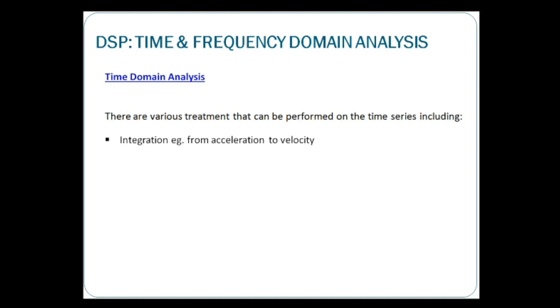So under this time domain analysis, you can do integration from acceleration to velocities. Then we have the velocity signals, and we can get velocity amplitudes, the velocity overall vibration. A lot of times your ISO standard compares with these velocities, RMS, overall RMS. Then you can immediately, in the digital domain, compare with whatever you are referring to in the standards, right? So it can be easily done in digital domains. You can do integrations, you can do differentiations, no problems. Similarly, another one is the bandpass filters.